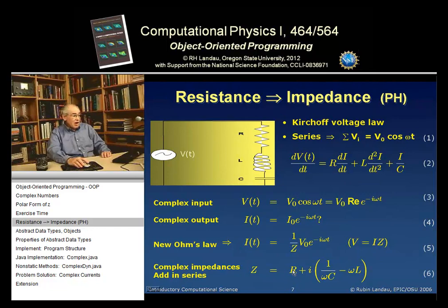The resistance, R, just gives us an impedance value of R. The capacitor, C, gives us an impedance value of i times 1 over omega C, omega being the external alternating voltage frequency, and the inductor, L, gives us an impedance of i times minus omega L. So they have an impedance, a resistance to current flow, which varies with the frequency and has a minus sign, which indicates in this case whether it leads or lags. But we'll see. So this is the analytic solution to our problem.